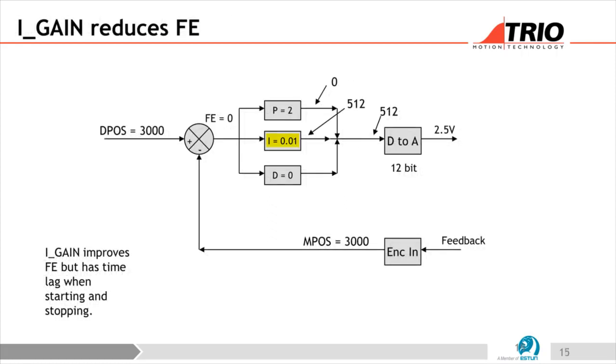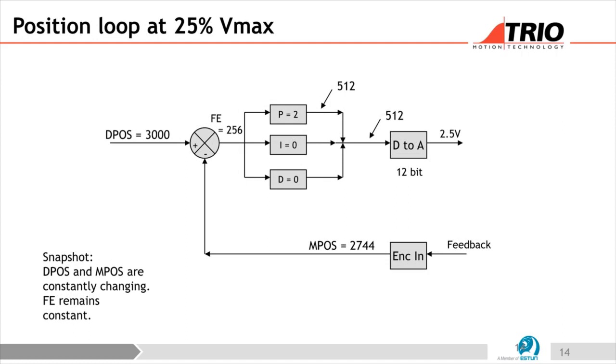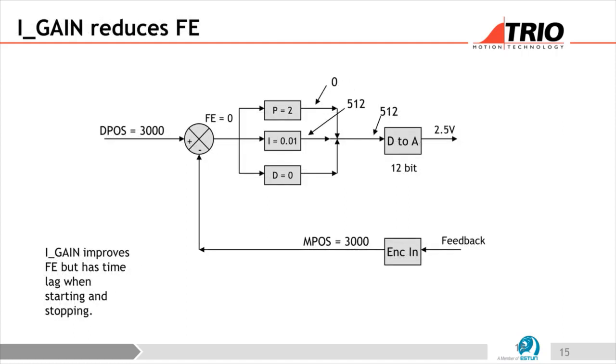It's quite small. So over a series of servo cycles, it will have said following error times 0.01 gives me an output. So first time round, remember my following error there's 2.56. So first time round, the output of this is going to be 2.56. And the next servo cycle, it's going to be 5.12. The next servo cycle is going to add it again.